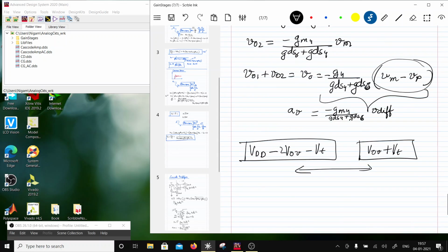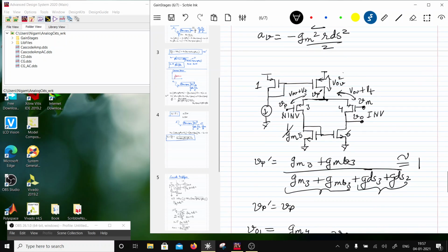Now what about the input voltage range, common mode? So the DC voltage is now a common mode. So what do you mean by common mode? It means that if the voltage to VP, with the voltage to transistor 3 and the bias to transistor 4, they are tracking together, right? They are equal, they're tracking together. Then there is a large input voltage range, right?